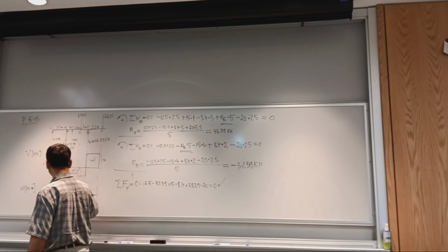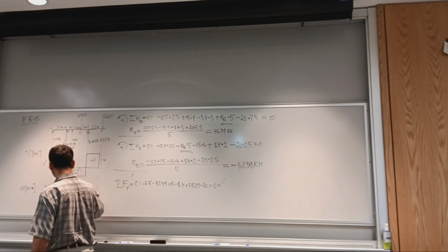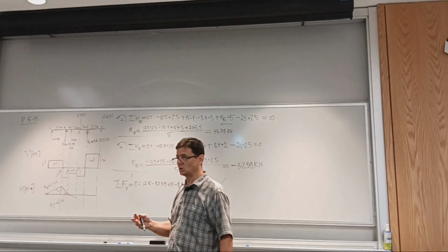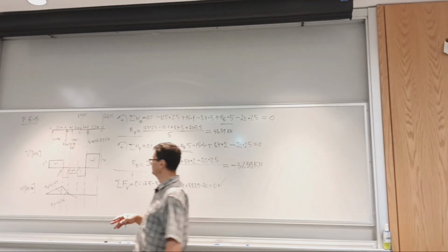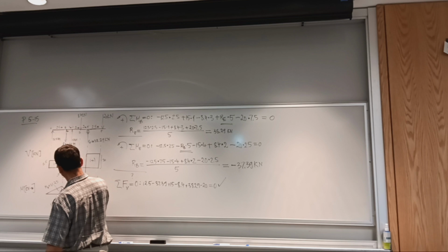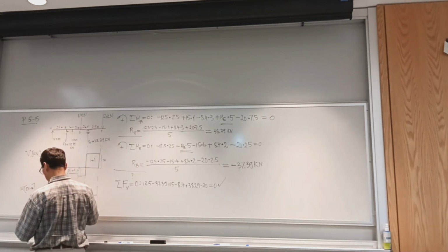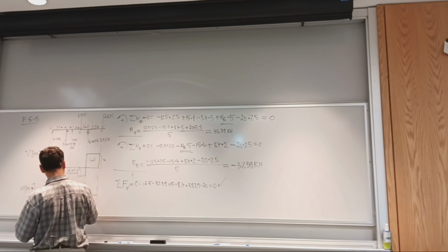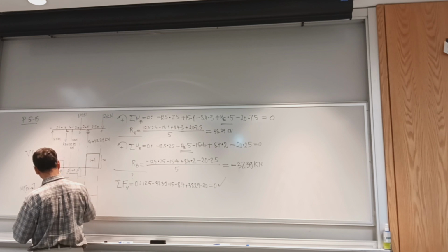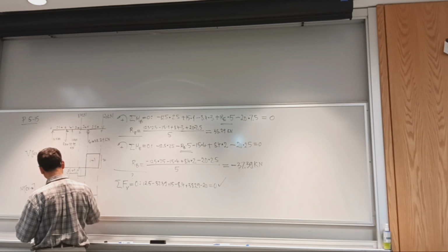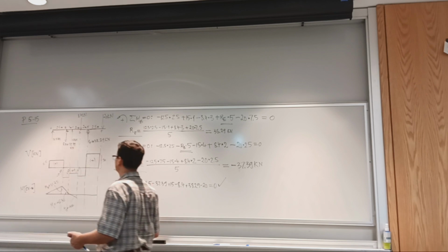So since the moment goes to 0, which is the derivative of the slope of the deflection, it means that the beam is going to have maximum sag here. Okay, so this value again, the moment at point D, was negative 13.42. Same units, kilonewton meters.